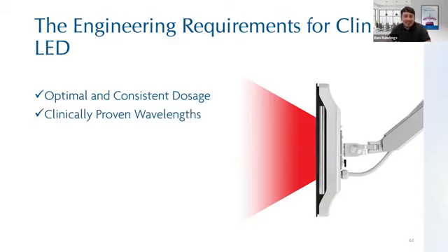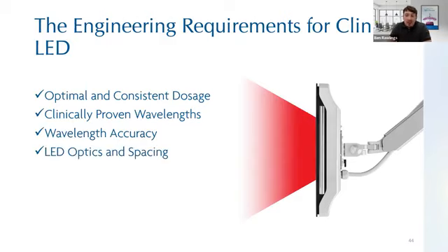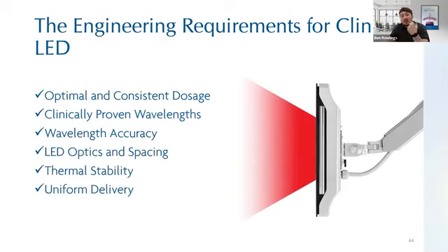So finally, just to summarize, what goes into designing a Dermalux device is optical consistency and dosage. So as Dr. Pablo said, if we're not hitting the right wavelengths, we're not hitting the right power parameters, we're not cooling the LEDs sufficiently, we're not eliciting response in the skin. So that's critical. It's accuracy more than power.